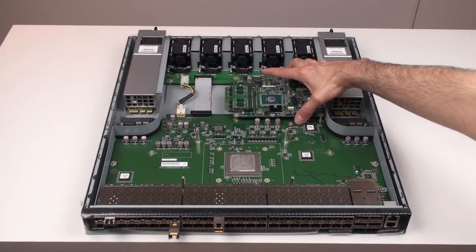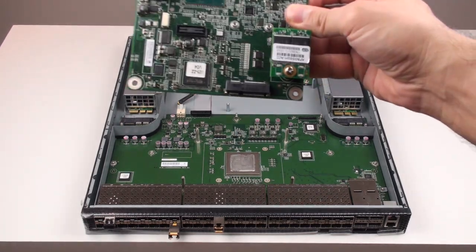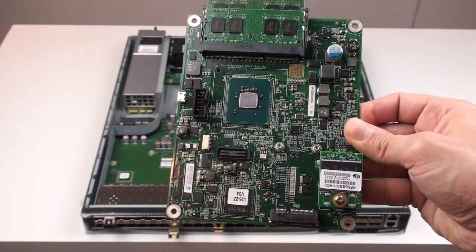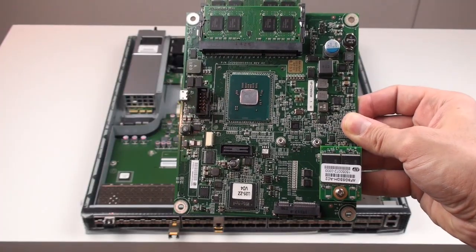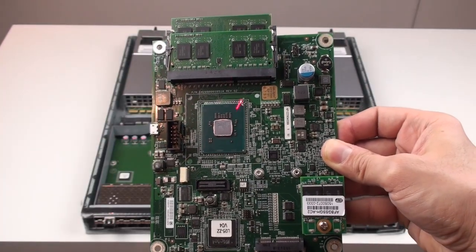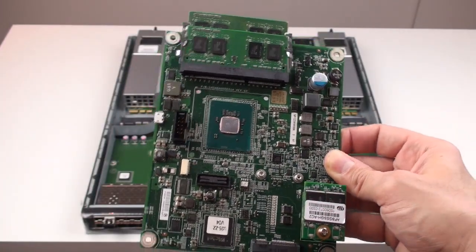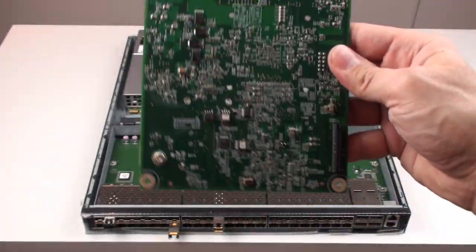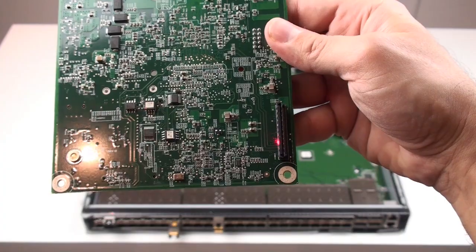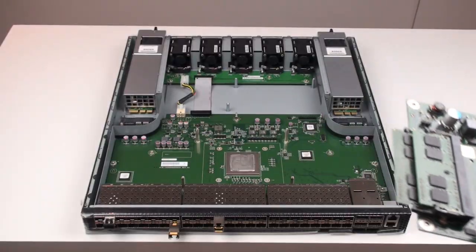All right, and this CPU module is also removable, so you can remove it from the board. And as you can see, it's a complete embedded PC. In the center, we got an Intel Atom processor, and on the top we got its memory module, which I think is 2 modules, each 4 gigabytes, a total of 8 gigabytes of memory. And here on the right side is a flash memory, where whenever you install any operating system on this board, that operating system will get installed inside that flash. And this is the connector which connects this PCB to the main motherboard of the switch.